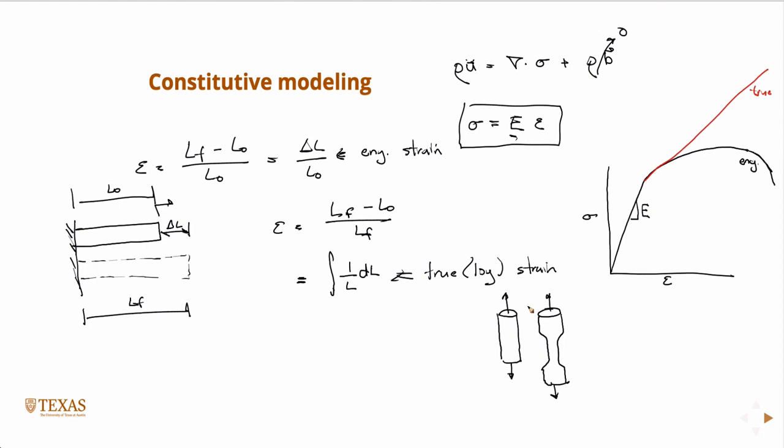Well, if you plotted the engineering strain, so engineering strain is just what we wrote there, and engineering stress is the force divided by the original area, right? This area, okay? Well, you'd see this softening behavior because the original area doesn't change, yet when this instability occurs, it actually takes less and less force to cause more deformation. So I don't have to pull as hard. Once I have this local instability, I don't have to pull as hard on my bar to continue to deform it, and you'll see this curve drop off.